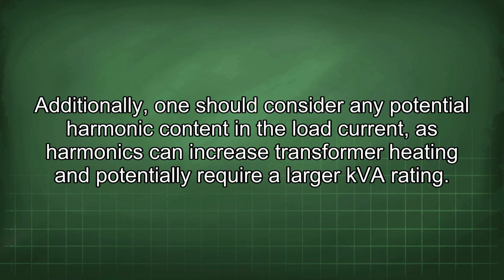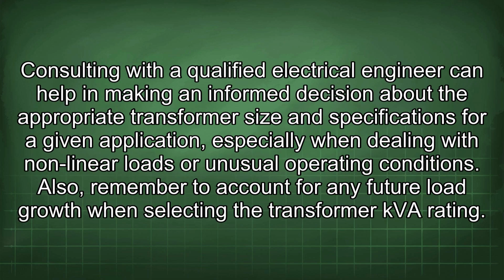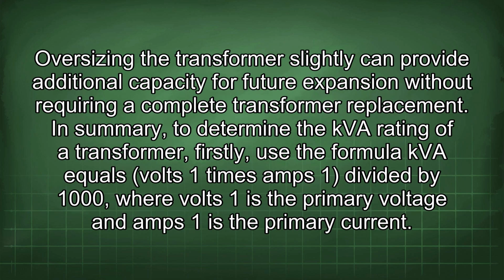Additionally, one should consider any potential harmonic content in the load current, as harmonics can increase transformer heating and potentially require a larger kVA rating. Consulting with a qualified electrical engineer can help in making an informed decision about the appropriate transformer size and specifications for a given application, especially when dealing with nonlinear loads or unusual operating conditions. Also, remember to account for any future load growth when selecting the transformer kVA rating. Oversizing the transformer slightly can provide additional capacity for future expansion without requiring a complete transformer replacement.